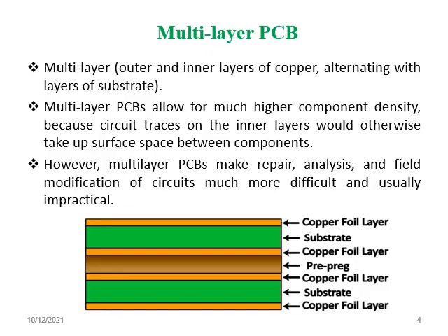And multi-layer: in multi-layer, it is constructed with a greater number of inner layers between the top and bottom layers. In this multi-layer PCB, we are able to adopt more electronic components, that is, we can bring the product into a compact size. The main disadvantage of the multi-layer printed circuit board is that modification of the circuits is much more difficult and usually impractical.